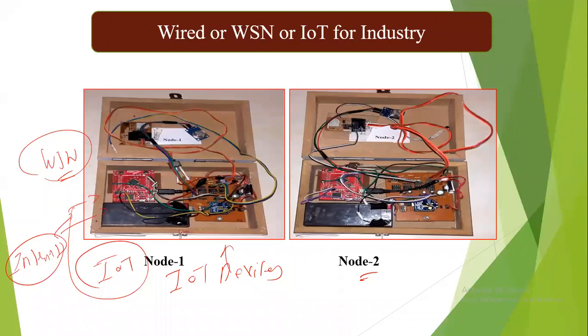Here you can see one small ARM board with an ARM processor. I have used it. It is a 32-bit ARM processor, along with a flash programmer on this board, and some header pins. Only the basic model is there. I have used it, and it is available at a cost of $5. Just purchase it and you get a 32-bit processor. Another PCB is designed for the sensor interfacing. For 5 to 6 sensors, signal conditioning circuits are designed on this board, along with the communication, that is Zigbee, and this is the battery. All these sensors are interfaced through this ARM board. The data is processed and sent through Zigbee to the base station.